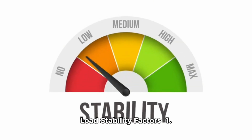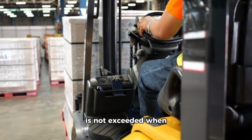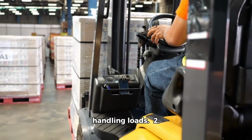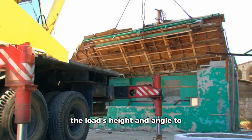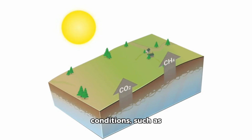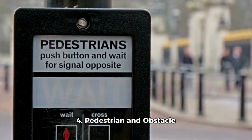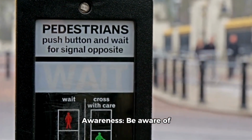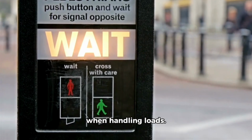Load stability factors. 1. Forklift capacity. Ensure the forklift's capacity is not exceeded when handling loads. 2. Load height and angle. Be aware of the load's height and angle to prevent tipping or falling. 3. Surface conditions. Consider the surface conditions, such as inclines, declines, and uneven surfaces, when handling loads. 4. Pedestrian and obstacle awareness. Be aware of pedestrians and obstacles in the surrounding area when handling loads.